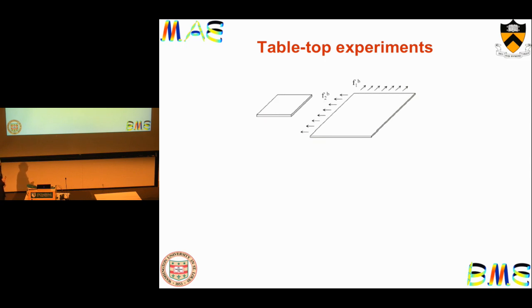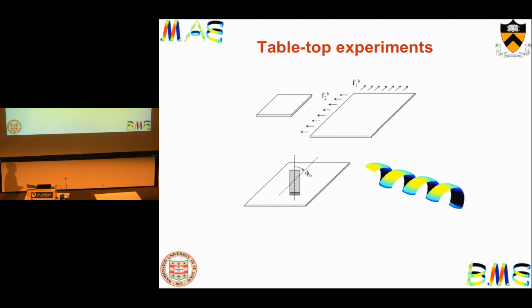So we take a sheet of latex rubber and we can pre-stretch it along perpendicular directions. Okay, so we can tune how much it's pre-stretched in these two directions, and then we bond a tape along a tunable angle. So this bonded two-layer system, upon release, would spontaneously deform into one of the helical shapes that you might have seen that we're passing along.